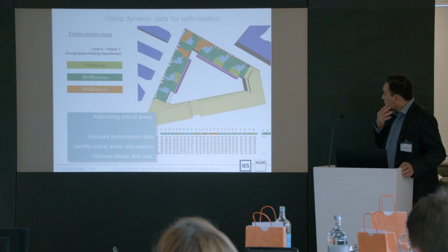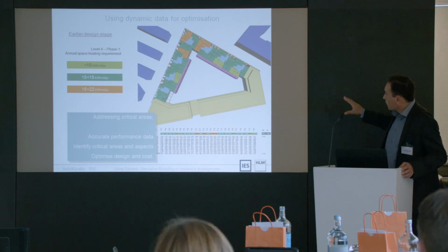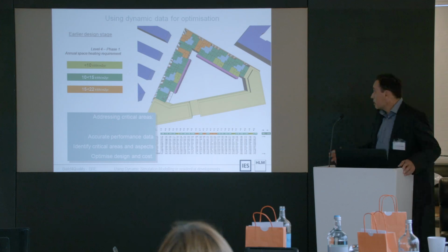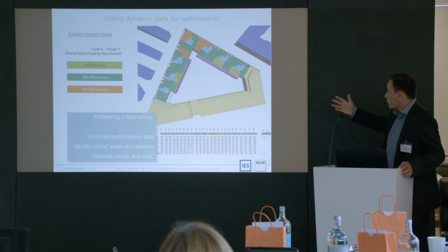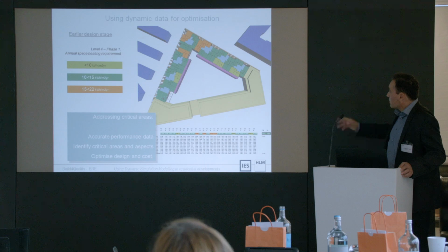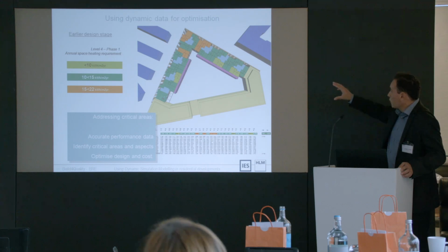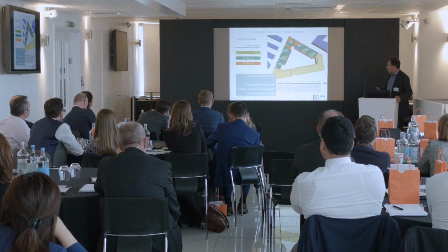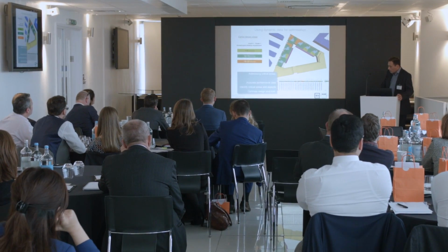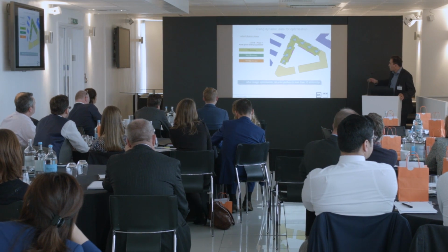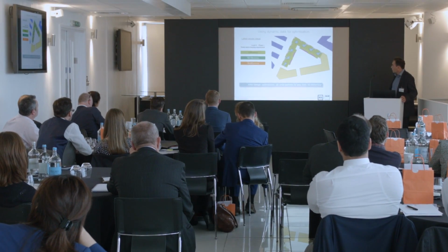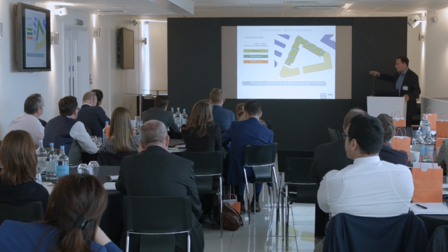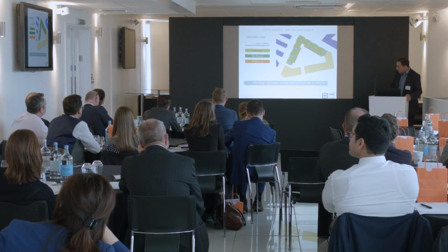And similarly, this is a distribution of performance over a floor plan at an earlier design stage. And at the time, that was already a good performance range. But a few apartments, as you can see, were not performing as the others. And then design proceeded, and after a few months, we had optimized things, and we got to a much better distribution of performance. Every apartment is performing below 10 kilowatt hours per square meter per year.